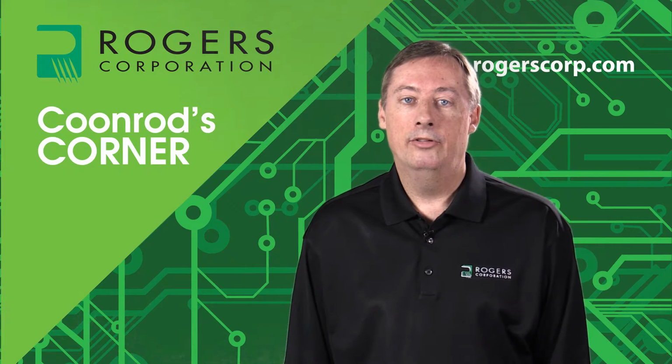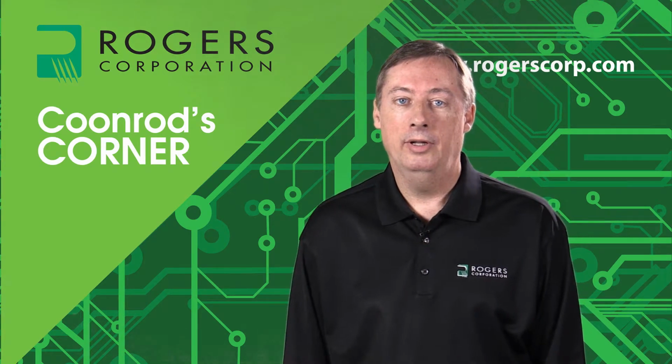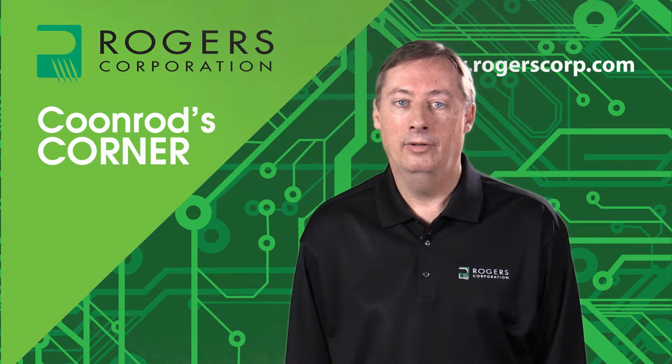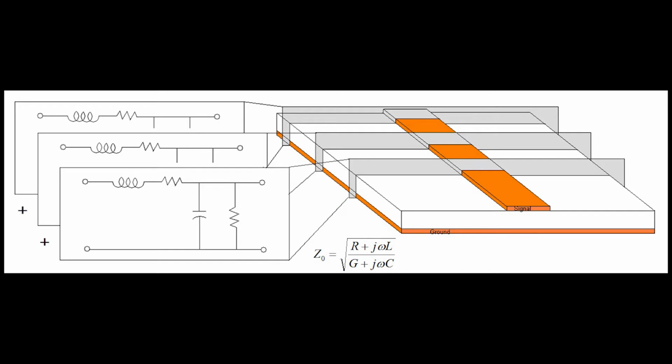The drawing shown here is just an expansion of the last drawing, really showing a little bit more of how the electromagnetic software that does these types of models looks at the circuit. What they're typically doing is field solving. So they're field solving slices of the circuit. For an infinitely thin slice they will solve for the fields, then move up the circuit a little bit farther in length and solve it again, move up farther, solve it again, and then piece it all together to get the overall performance.